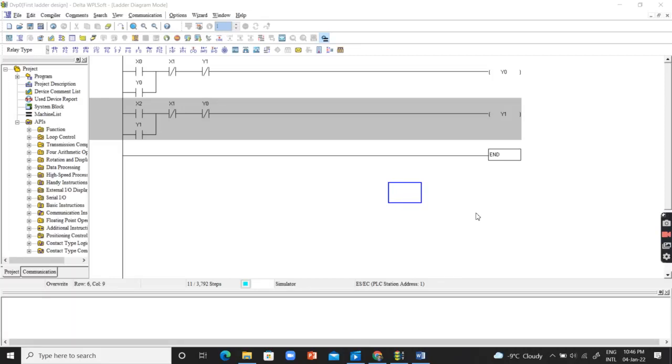All right, students. So we are now moving to study the ladder logic for the interlocking circuit, and it has a very high number of applications. For example, if you want to turn a motor in clockwise or anti-clockwise direction. The motor can only be turned in one direction, and if someone by mistake presses both buttons simultaneously, the motor would be under a lot of stress, and the bearings and the internal cage of the motor will be totally destroyed, right?